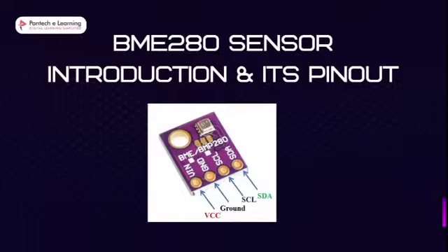It is mostly used in web and mobile applications where low power consumption is key. This sensor uses I2C or SPI to communicate data with a microcontroller. Although there are several different versions of the BME280 available in the market, the one we will be using is based on the I2C communication protocol. You already know how I2C works, right? With the BME280, the STM32 NUCLEO acts as a master and the BME280 sensor acts as a slave, because it is an external device.